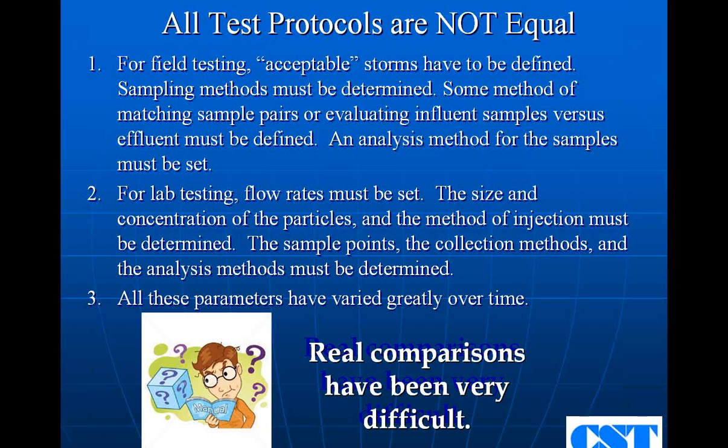For lab testing, you have to set a flow rate. And in general, you want to build a curve. Most people will take a target flow rate and test at 25%, 50%, 75%, 100%. That's kind of what NJDEP has asked people to do at New Jersey DEP. And then NJDEP is interested at 125% of that flow rate. When we tested in the lab, we went up to, I think, 9 times our flow rate. We really wanted to blow everything out of that device if we could. But in all of that, in a lab test protocol, you have to decide what you want to test: the size and concentration of the particles, particle size definitions, everything.